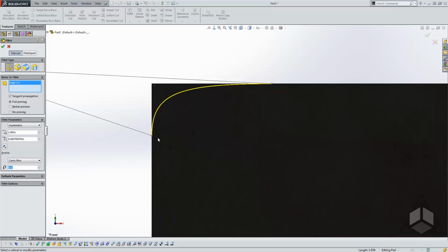And again, the nice thing with this is we're not having to worry about any of those tangencies inverting or anything like that if we were to cut this out with a spline or something like that. So very easy to use, very robust, and we get a pretty fine amount of control out of it by just supplying a couple of values. And again, I like to just kind of tweak. These obviously would be used for more free-form kind of shapes, but I like to be able to just kind of view that and tweak these out to the shape that I want, especially if I'm trying to match a sketch or an artist rendition or something like that. So neat control. I think added capabilities for not too much extra work to be able to get those kind of complex shapes out of it.